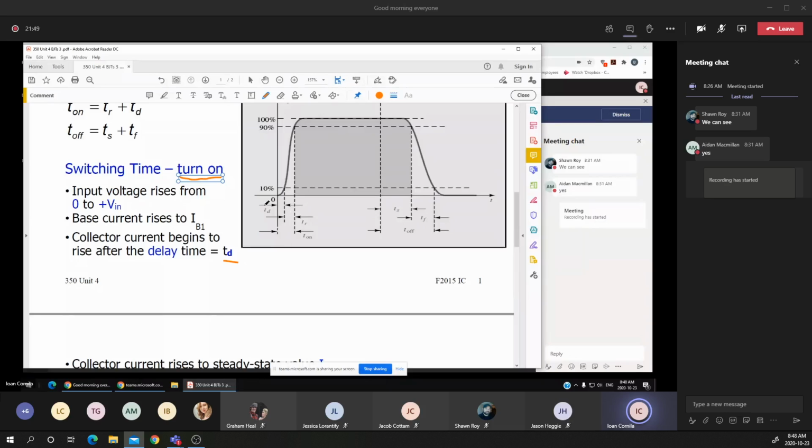The TD, again, is just the amount of time required for the transistor to supply enough current to have the electrons flow from the emitter to the collector, and on top of that we have to add the capacitance between the base and the emitter and between the base and the collector. From 10% to 90%, those are the limits used most of the time in calculations.